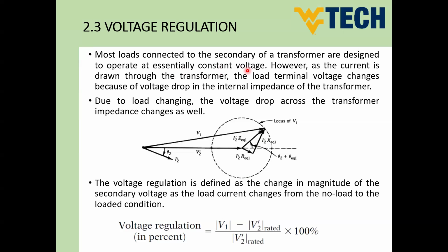Otherwise, this may affect the connected loads. You know, guys, we have one type of protection called under voltage protection, for instance. We use it to avoid having undervolt across loads in order to avoid higher current absorption from the loads.